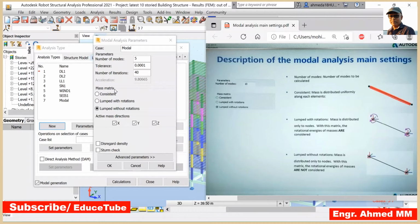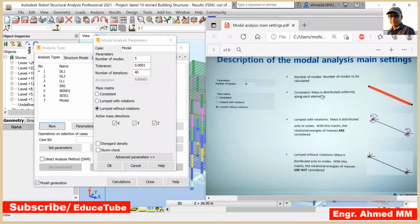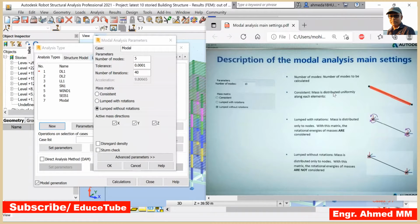Now for mass matrix: consistent, lumped with rotations, lumped without rotations. Consistent, what it says, mass is distributed uniformly along each element. By seeing this figure, it's very clear to us what is written here. Distributed uniformly, you can see here. But for the second one, lumped with rotations, mass is distributed only at two nodes. We can see node here, node here.